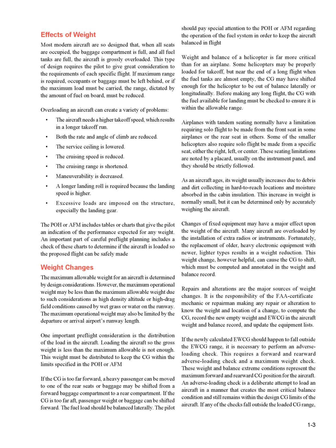Overloading an aircraft can create a variety of problems. The aircraft needs a higher takeoff speed, which results in a longer takeoff run. Both the rate and angle of climb are reduced. The service ceiling is lowered. The cruising speed is reduced. The cruising range is shortened. Maneuverability is decreased. A longer landing roll is required because the landing speed is higher. Excessive loads are imposed on the structure, especially the landing gear.